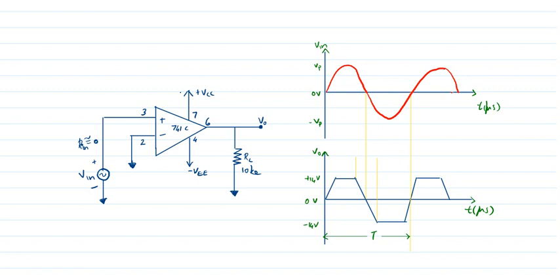That is, I have drawn here a sine wave, and the peak voltage is VP, also shown here. In the case of open loop configuration, the gain is very large. So the output will go to about 14 volt. If we apply the input as plus 15 volt and minus 15 volt, the gain is very large, so the output will go nearly to the input voltage. Almost it will come to 14 volt.